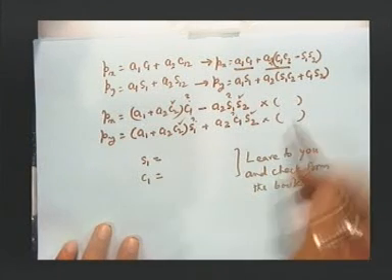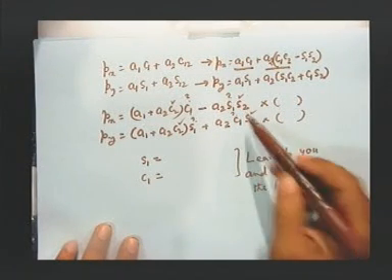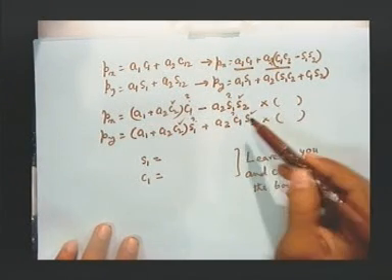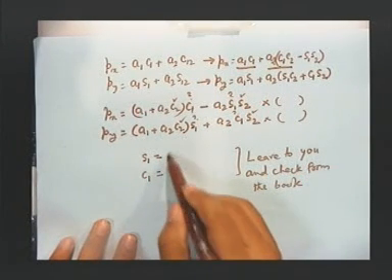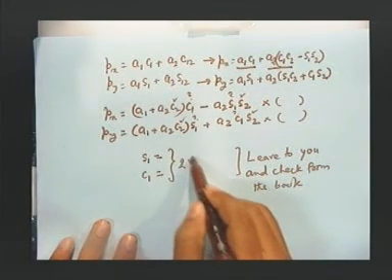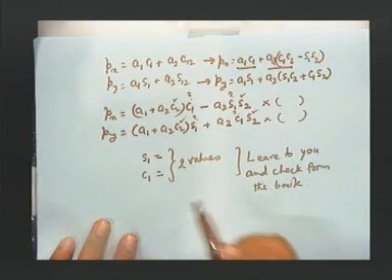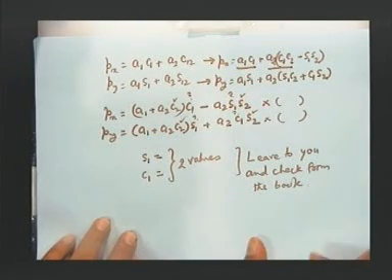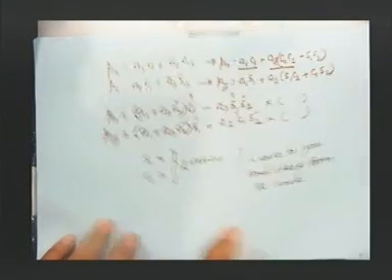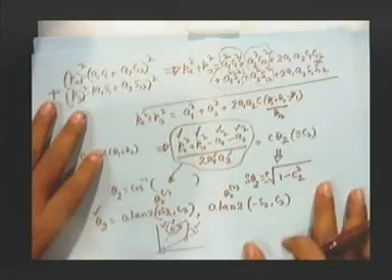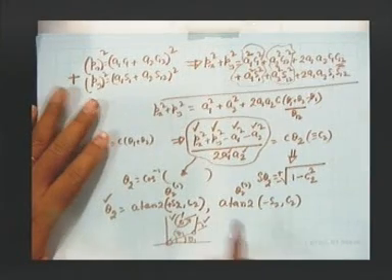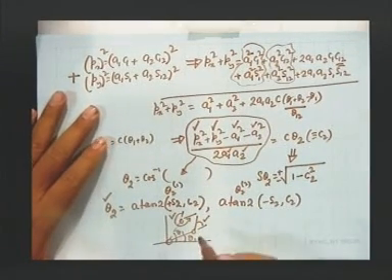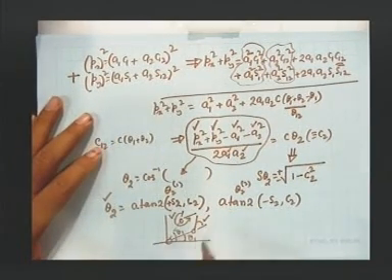And since sin theta 2 had two values, plus and minus, obviously you will have two values corresponding to your two theta 1 values. I turn this page and show it here. So, this is one theta 1 and this is another theta 1. So, for a 2 degree of freedom robot arm, you will have two solutions.